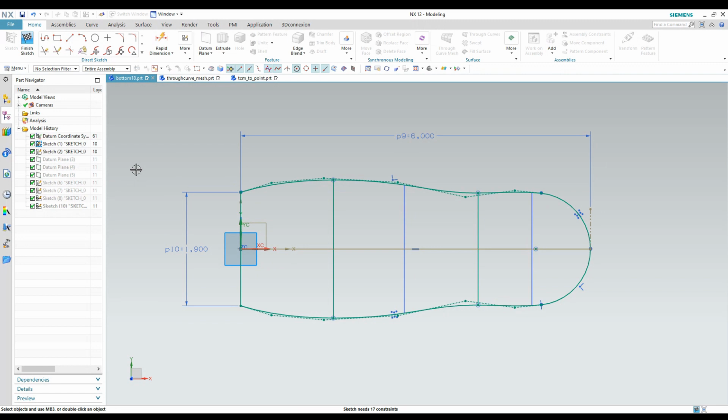So what I usually start with is probably the top profile on a part like this. Again, it's going to depend on what the shape of the part you're creating is, but this profile is what the shape is going to look like looking down on the top of the part. And I'm going to use this to define some things for my other strings in the other directions. So when I start this shape, obviously this is what the profile is going to be. This is going to be another part that comes to a point back here also. So just like the last one we made, one of our primary strings is going to be a point.